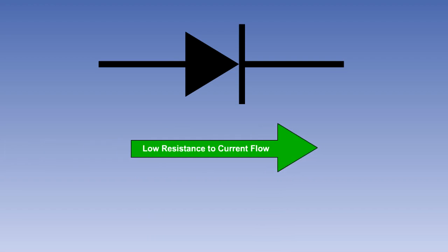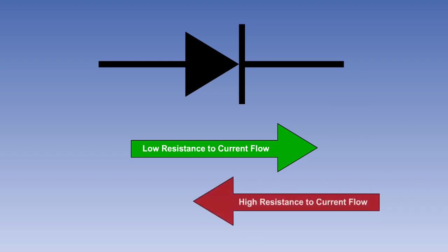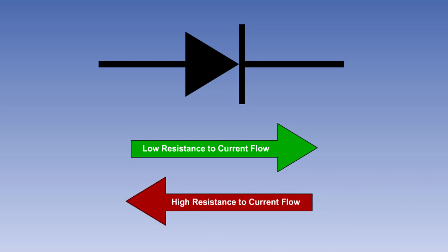A rectifier is a device which will convert alternating current into direct current. The most common rectifier in use in aircraft systems is the solid-state diode rectifier. The electrical symbol for a diode rectifier is shown here. The diode is a semiconductor device, and its operation is fully explained in the lesson on semiconductors. It has a very low resistance to current flow in the direction of the arrowhead, and a very high resistance in the other.